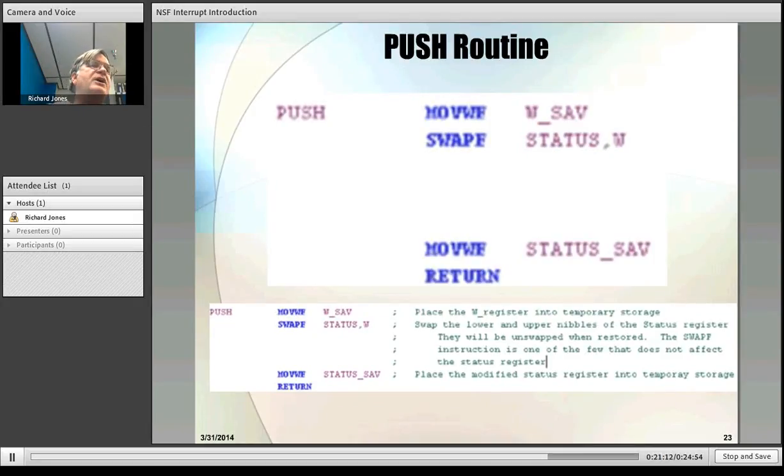Now it should be noted here, I've written this particular routine as a subroutine. Okay, in general this is not a good idea because it's using up a stack level. But if you've written a program where it is not necessary to worry about the stack level because we're not going to be nesting too many of them, and we're not worried about using the clock cycles that are used because of a subroutine, then this is not a bad way to go. I've shown the actual commented code below this section, although I'm not sure you'd be able to see it on your screen. It's in the handout.